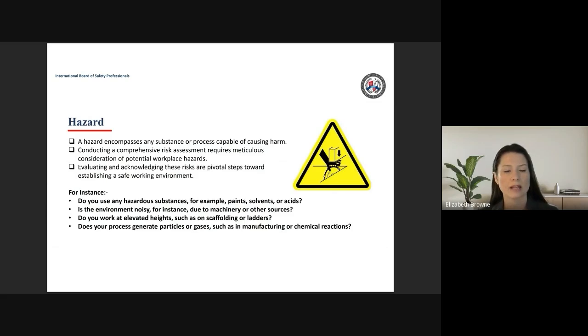You know, do we have elevated heights? In a general industry setting, any worker that is exposed to a height of 4 feet or more should be guarded or protected against fall. If they're on scaffolding or ladders, there are some exceptions to that, and the heights are different in which a worker can be exposed to those heights, but we have special work practices we must follow.